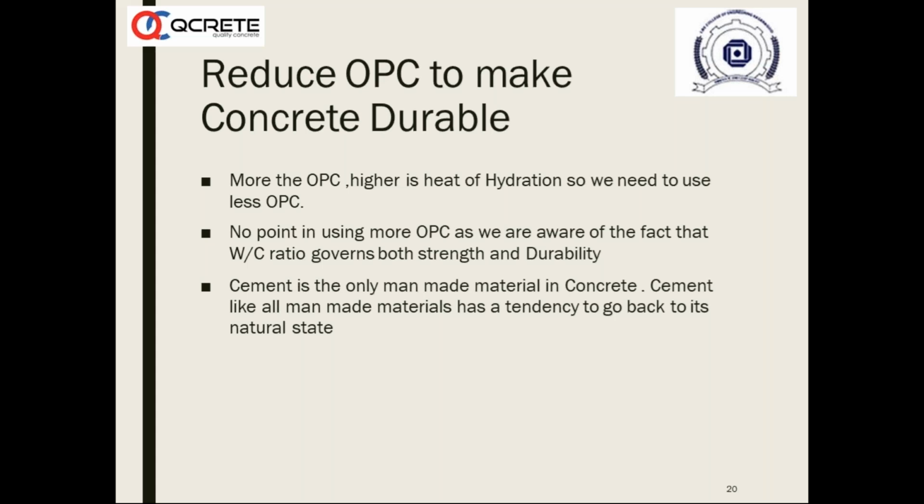because the surface temperature is influenced by atmospheric temperature. It will be cooler. If the difference, temperature at core minus temperature at surface, crosses 14-15 degrees, cracks will develop in the body of concrete. Hence, it is going to cause disaster for concrete structures if we are using a high amount of OPC content. So heat buildup has to be contained, lessened.